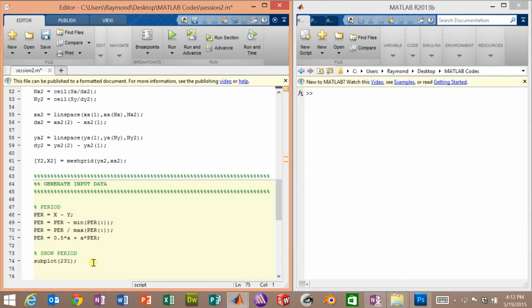Now rather than p-color, I like to use the imagesc command. It's a more intimate tie to how the data actually looks in your arrays. It shows the pixelation. p-color does some other things. p-color is great for generating nice, smooth, high-quality pictures for publications, but when I want to visualize my data, I like using imagesc a lot.